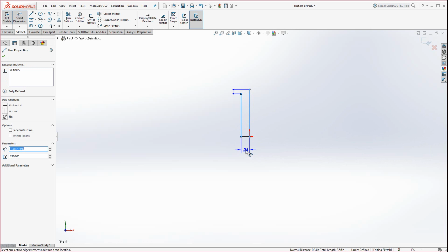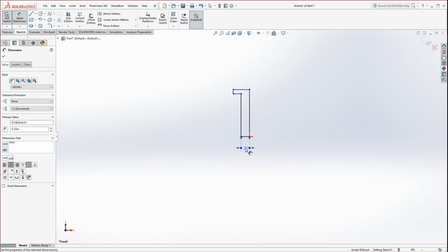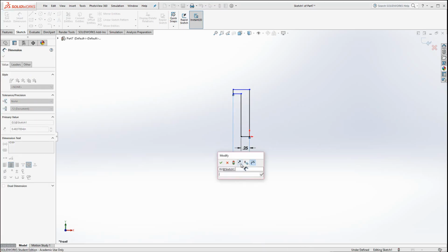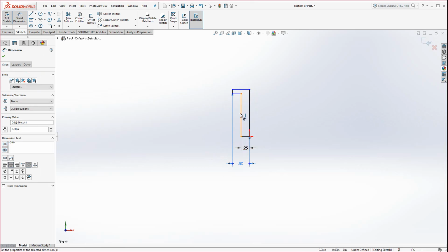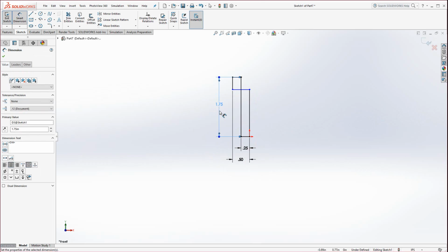If you recall in exercise 2, you need a center line. So when it's two object lines, you're not going to get it. But in this case, that's fine. I'm just going to go with 0.25 because I know the overall diameter is 0.5, so this is half of that. Now I'm going to click on this to this, and this would be 0.5. The length of the shaft is 1.75. And then I'm going to hit escape.